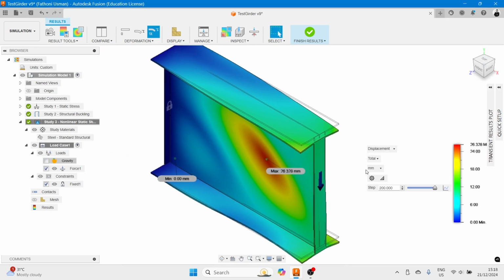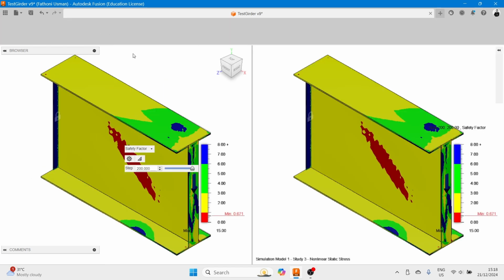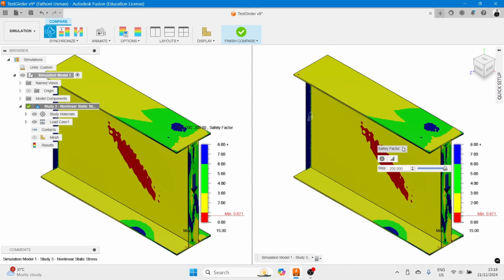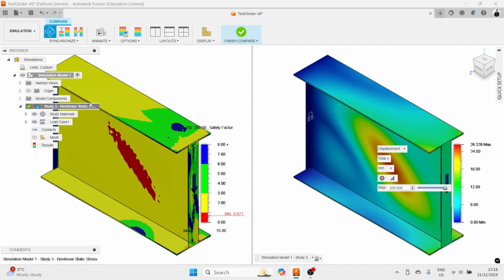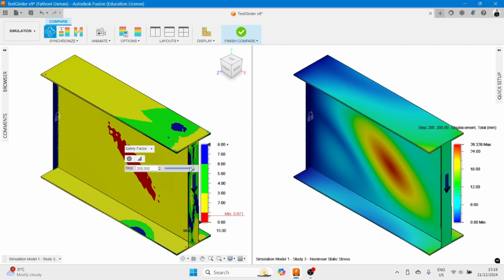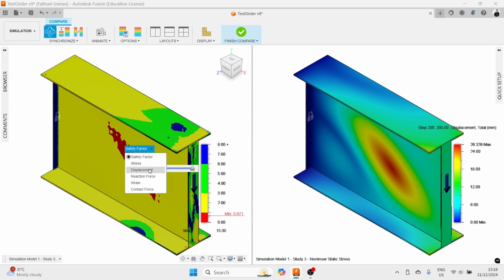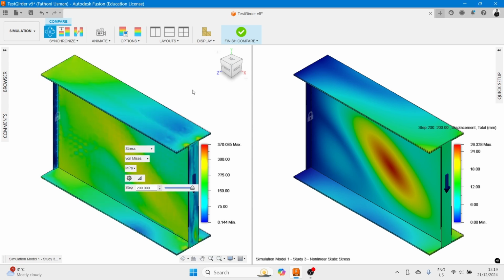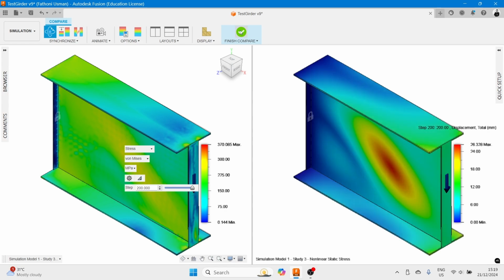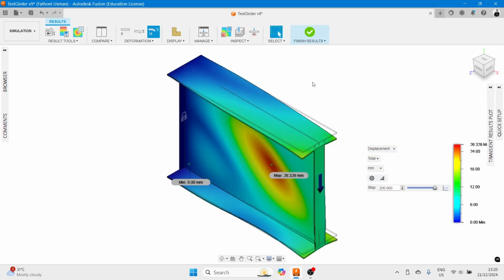Okay, that's all. You can explore this one. You can also do a comparison here. Click compare, and you can give displacement here. Then you can hide the browser, and select the strain and stress. Normally the stress and the displacement are sufficient to determine when the yield is reached. Then click finish compare to end this one.